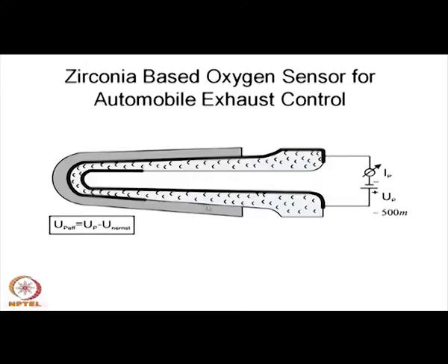And then this is a kind of porous shroud which protects this particular thimble, and this black area is actually the electrodes. Okay. So, the outer electrode comes up to this end, and the lower electrode also comes through the inside wall up to this end. So, you can measure the EMF from these two points.